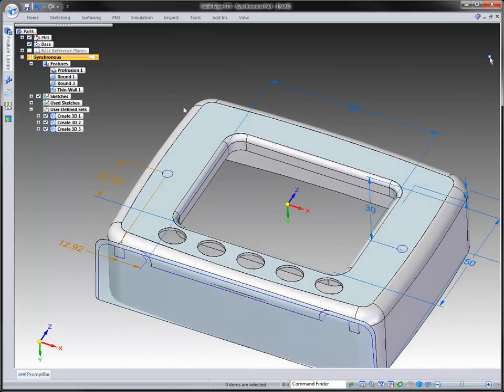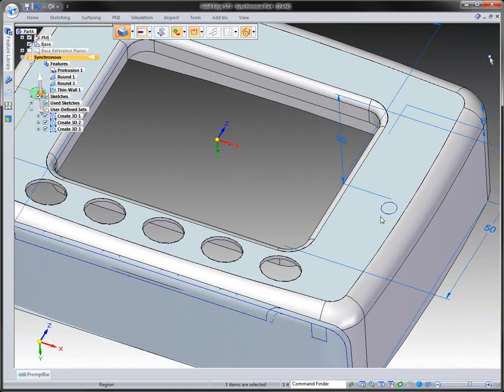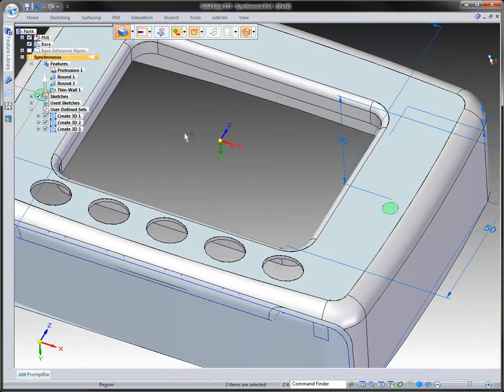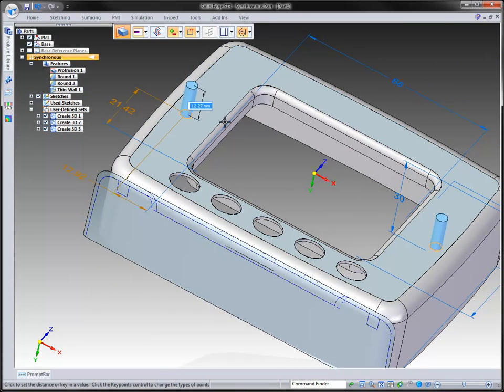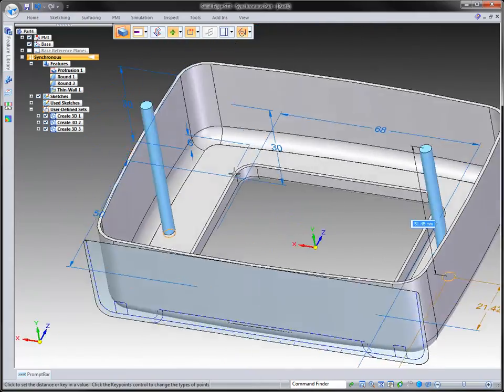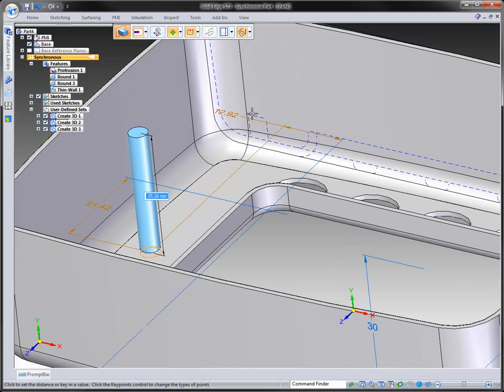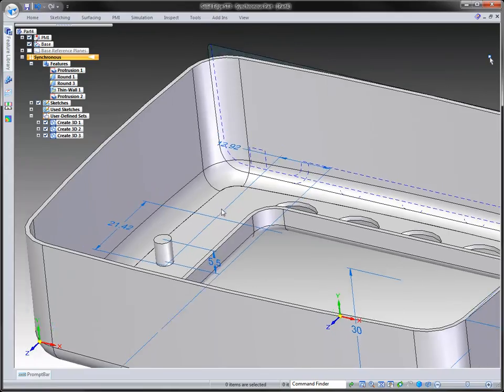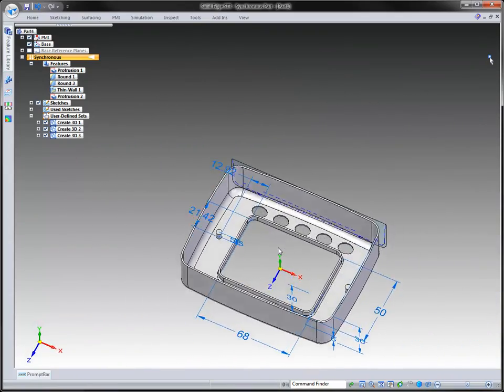Next, we have some mounting posts that we need to place inside of our part. So we're just going to come over here, grab that information, and we can pull it up and see that we have a protrusion. If you push down through the model, we'll actually get a cutout. But we want to tell the system, go ahead and add, no matter which direction I go, I want you to add that information. But what is the height of this part? Well, the height of it goes to this endpoint right there in my model, and you can see that our dimensions now attach, and now I have a new dimension added there as well.